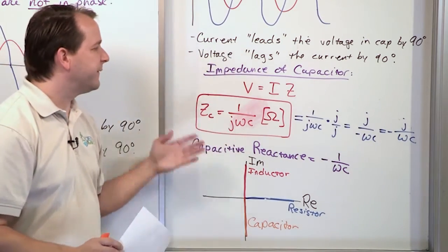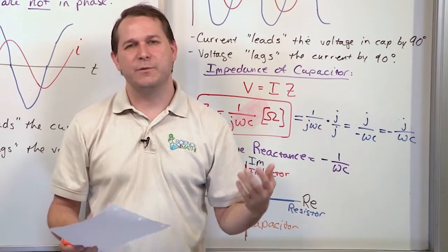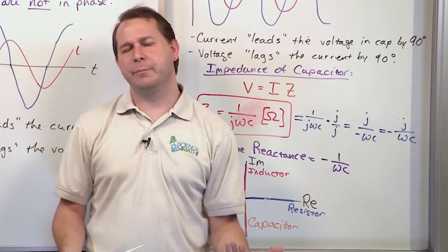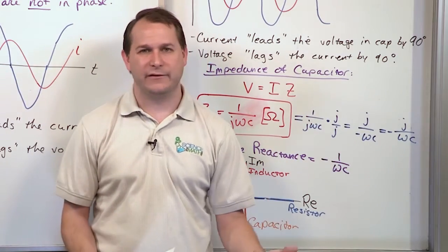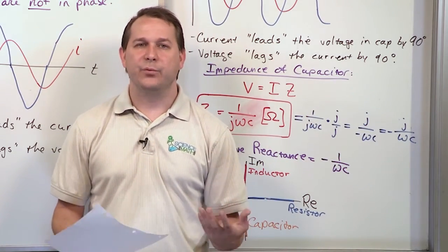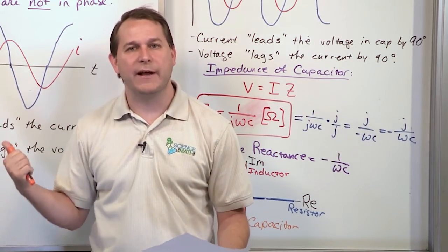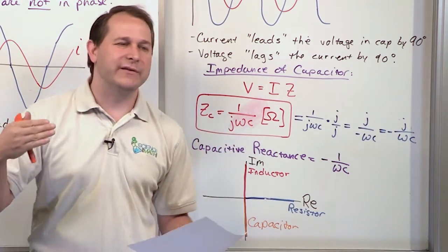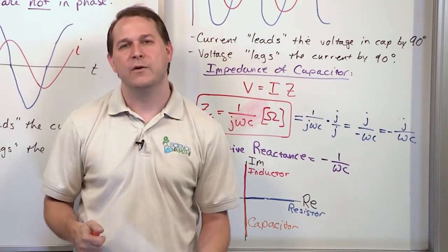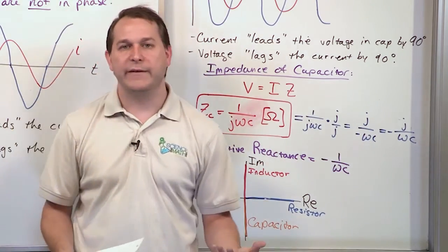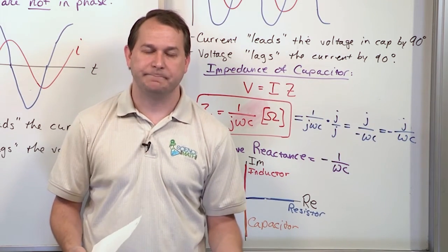So it's a little bit extraneous. It's not something you'll probably be tested on, but when I learned it, I was wondering why inductors are positive imaginary and why capacitors are negative imaginary. And the reason is that the voltage current relationships we see when we plot the cosines trickle into the representation we use with imaginary numbers, and it shows up in how and where they are on the complex domain.